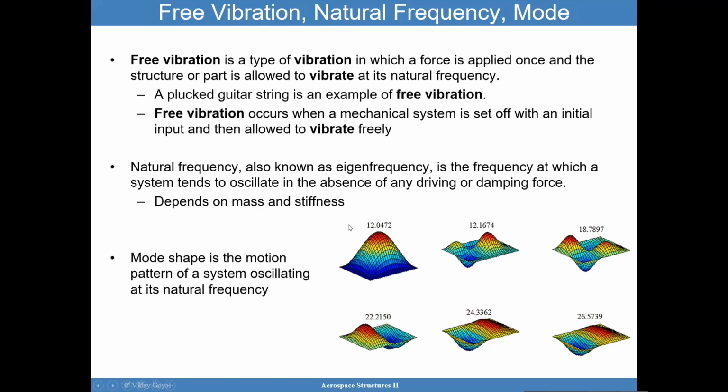You can see here various mode shapes. So what happens is that if you were to impart an initial motion, it's possible that this particular plate, as an example, can take a vibration shape that looks like this one. It's possible. And these are the fundamental frequencies of this plate. And these are in hertz, by the way. So 12 hertz, 18 hertz, 22 hertz, 24 hertz, 26 hertz, okay?